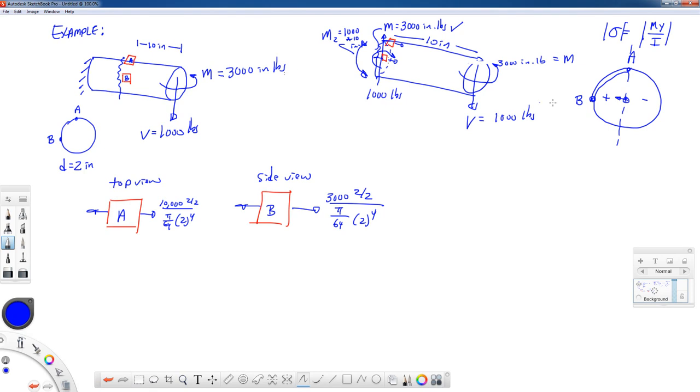At point B, which lies on the side, if we sketch in the bending axis, the 10,000 inch-pound bending moment is bending about this line, and that line goes through the centroid. Now the y distance as far as that moment is concerned is going up this time. And point B lies on the bending axis. It has no stress from that moment at point B.